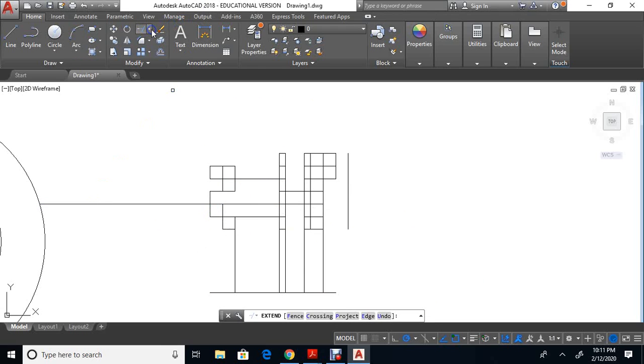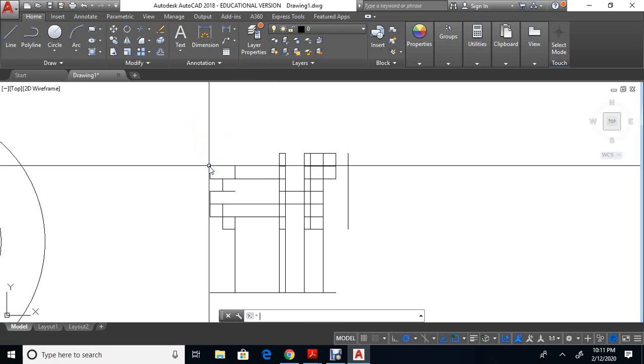Again, the trim the other way around, so I click here, I go to the trim command, I click enter after I pick the command, just hit enter, and then I can start cutting objects or cutting pieces like here and here. Now if you can't trim something, you can always use the erase command after, and you can always erase what you can't trim. Okay, and that's it for the offset, trim, and extend commands.